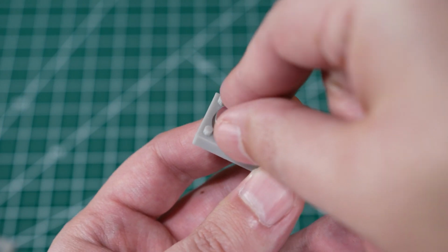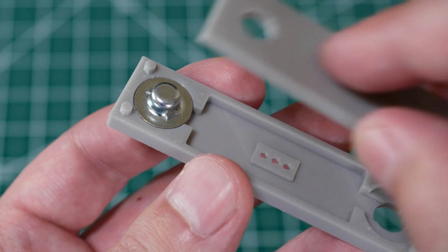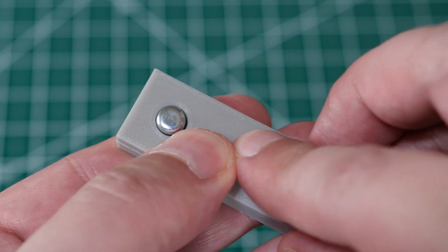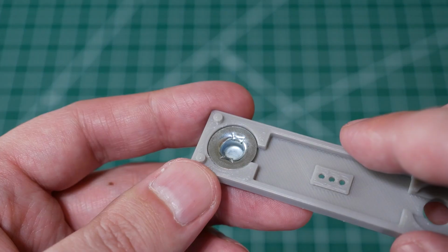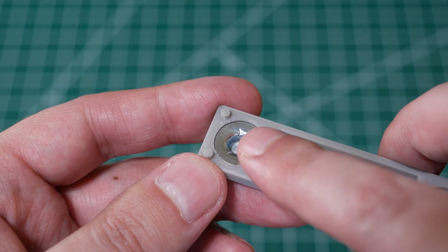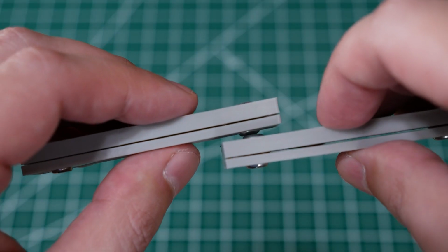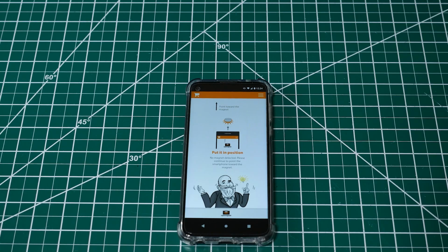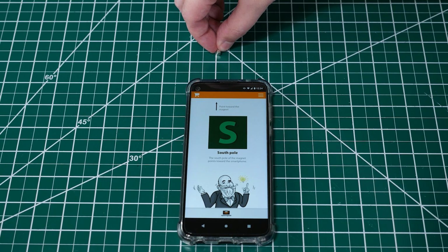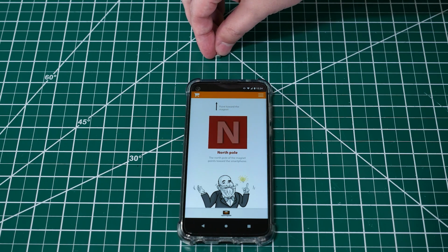So we take a couple of nuts and put them back to back like this, and when we snap the top and bottom together, it'll create a contact point on both sides. We put magnets in here, oriented with the correct polarity. It will attract the contacts from the other components. If you're not sure about the polarity of your magnets, there are apps you can get on your phone. I think this is a really cool use of the magnetometer that's normally used as a digital compass.